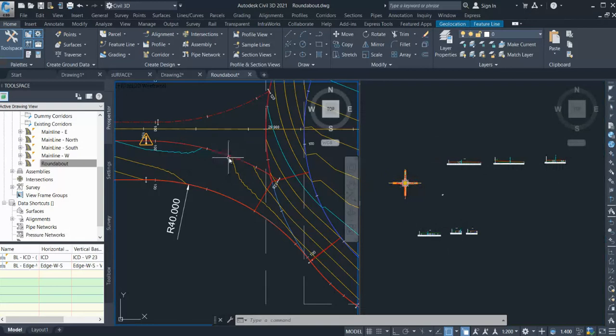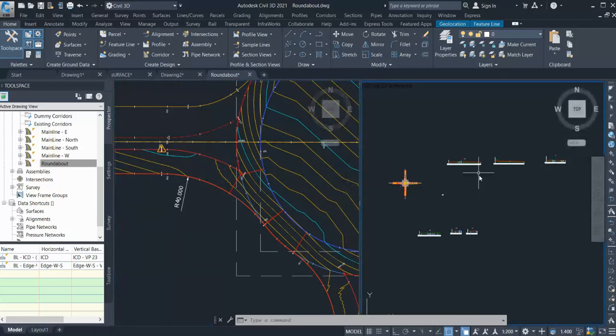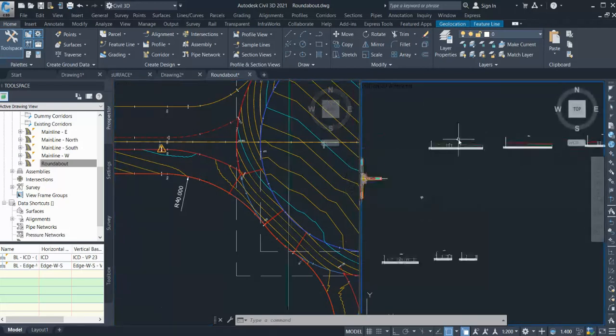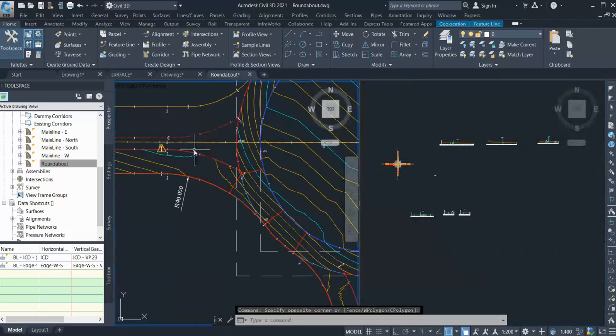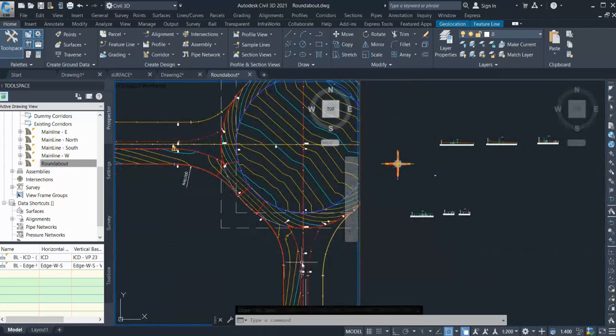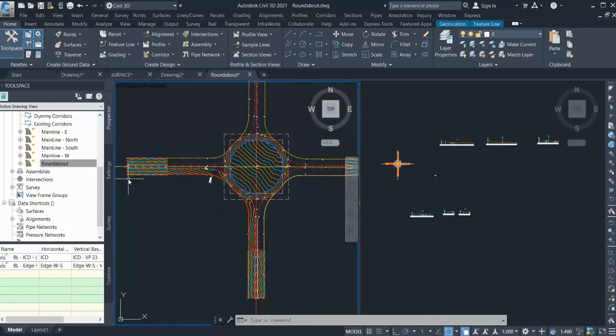You should not have flat areas because they will create drainage issues. So you need to be aware of those things, and then you have to play with your profiles of roundabouts and everything to remove those. But this is just for teaching purposes, how you can create the complete surface. What I did, I just did a continuous alignment for this.